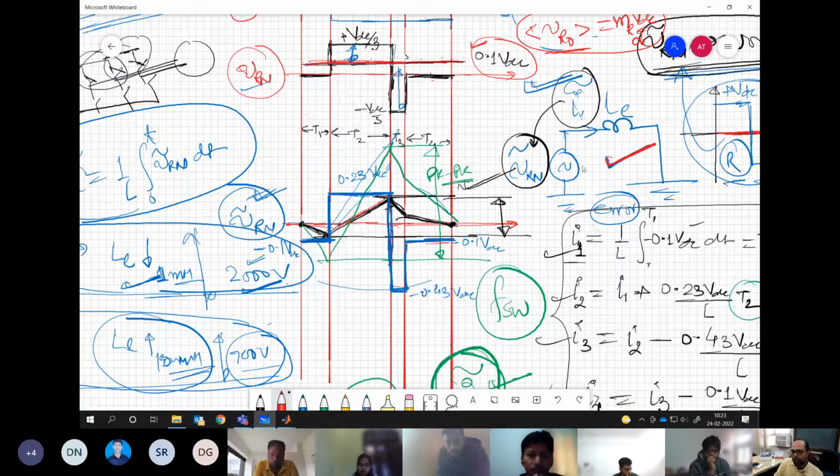So what it is having is basically a simple inductance, and because these voltage levels are DC, the current ripple looks like a set of linear waves, a set of lines. We are not approximating anything over here. So the ripple you see mostly looks like a triangular ripple. The reason is that we are talking about voltage levels which are kind of DC, and we have only an inductive element over there, so we see almost linear current in every zone.